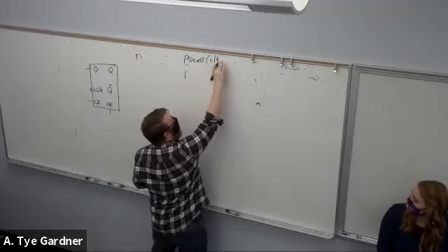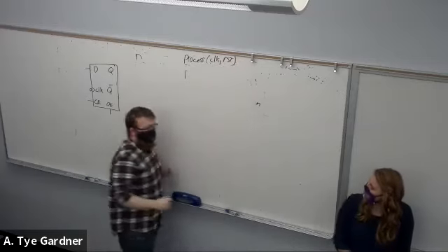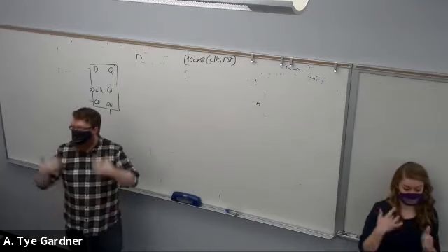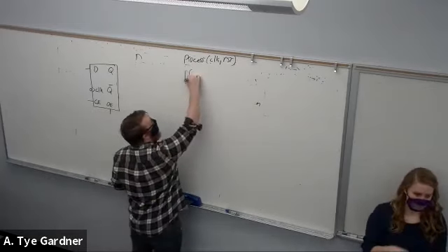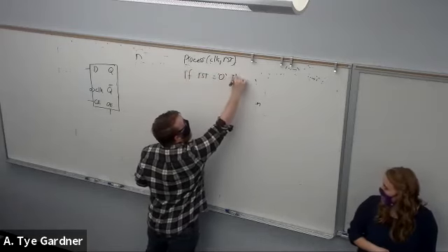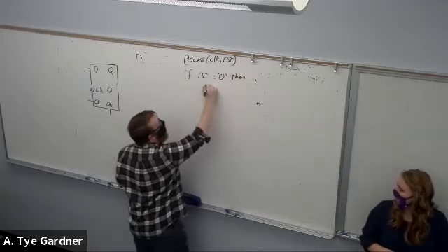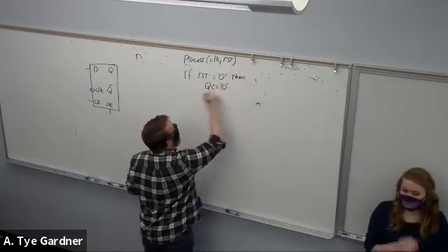The first thing that we do is we add reset to the sensitivity list. That way we can respond instantly to it, right? And then I just say if reset is equal to 0, then Q gets assigned to 0.